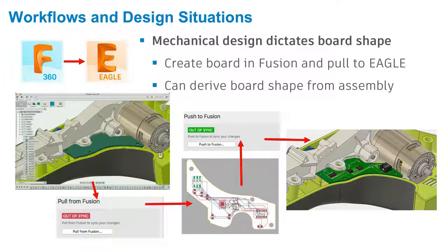Yes, sir, please. Just wondering if the PCB sketch, does that follow the same rules as a normal Fusion sketch so that, for example, you've got mounting posts and those need to change mechanically, the sketch would follow and update everything downstream? Absolutely. The important thing to note there is only the Fusion board shape is linked in that way because if we copy the Eagle sketch like we showed in the first example, that Eagle sketch won't update if we change the board profile in Eagle and then push in a new version. We'll still see the old shape there, so we need to do it again.